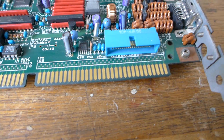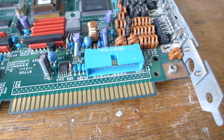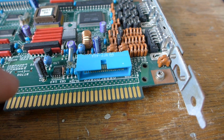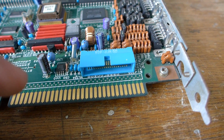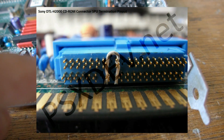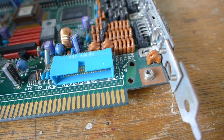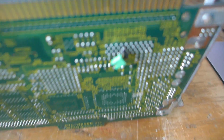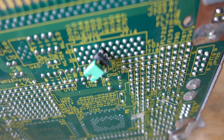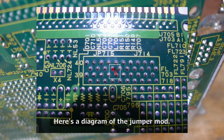But if you don't have either CD-ROM modules, you would need to have a terminator connector installed, which is just a Yamaichi NFS 40A connector, which would go here, and then we'll have a piece of wire that connects two pins together as the termination. Or you could just solder a little jumper like this one to replicate the terminator connector's functionality.